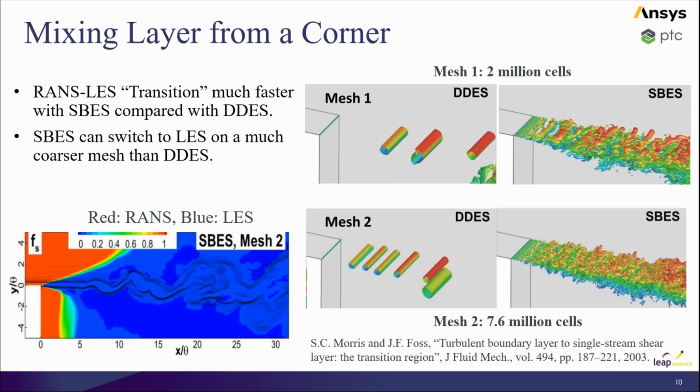So this is essentially where we're at with these type of models, and SBES can be used for an enormous number of applications. We've got a couple coming up, but the sorts of other things: heat transfer when you've got complex behavior, sound, so noise prediction, you can get actual fluctuating pressures out of this, which are really good. It's really good for mixing. If we've got reactions that depend on mixing, then we're going to get a much more sensible mixing profile out of this, so in combustion, than we are with something like this.